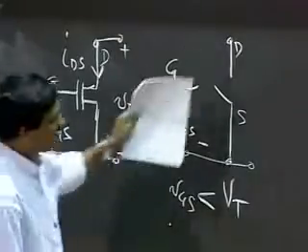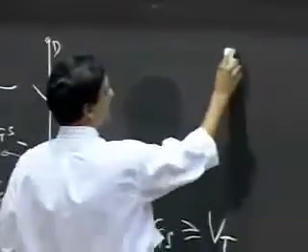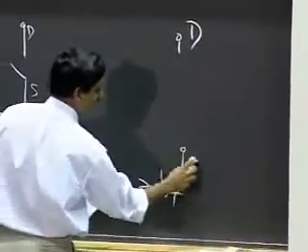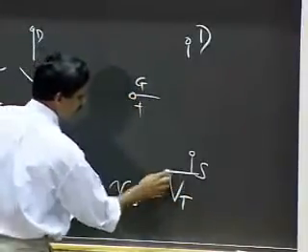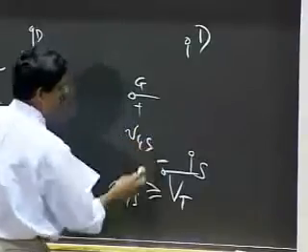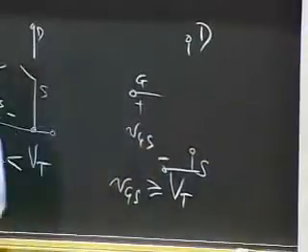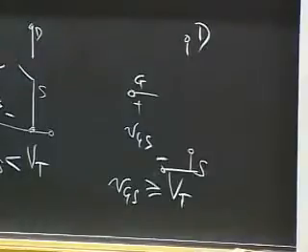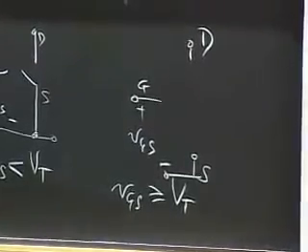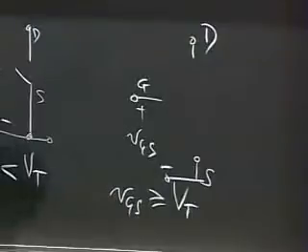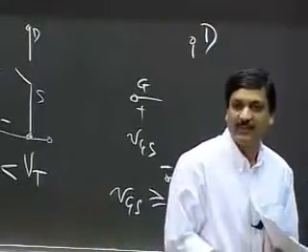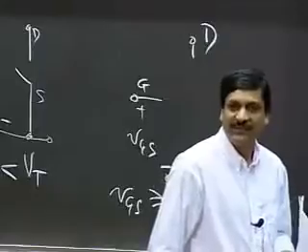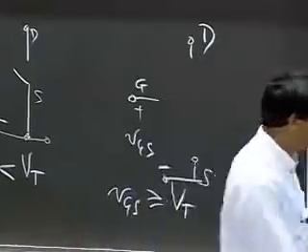So let me pause for a second and leave this space blank here, and let's do some investigations. I won't draw in anything yet. You will figure out what it looks like yourselves under certain conditions. So what I'll do next is put the MOSFET, apply some voltages on it, observe the current versus VDS behavior and plot that on a scope and take a look at it.